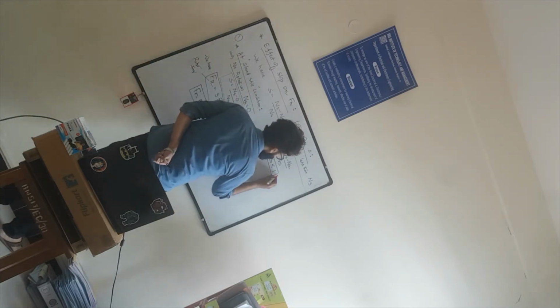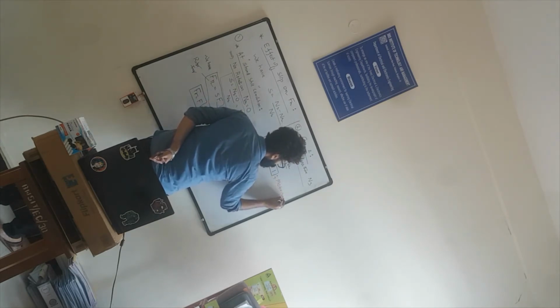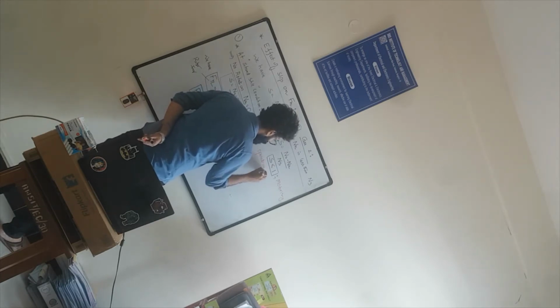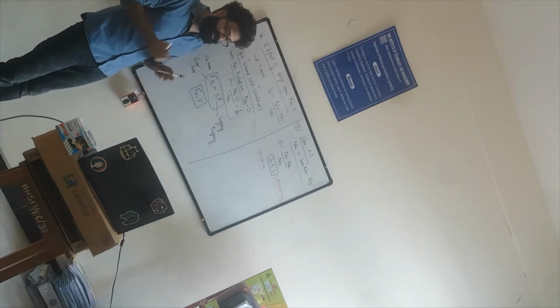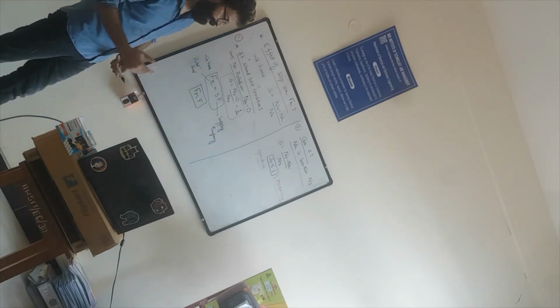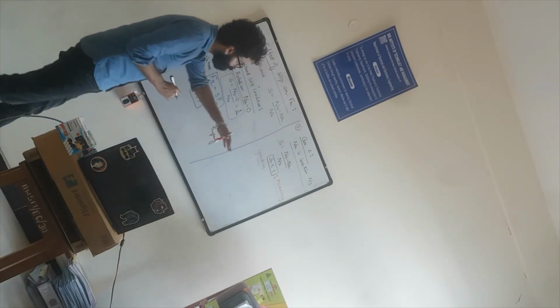Okay. So this condition is always called motoring operation. In the sense, the given induction machine operates as a motor, an induction motor. So for a motoring operation, the slip value is always less than unity. It is greater than 0 but less than unity. Okay. Fine. Now, what implication does it have on the frequency?